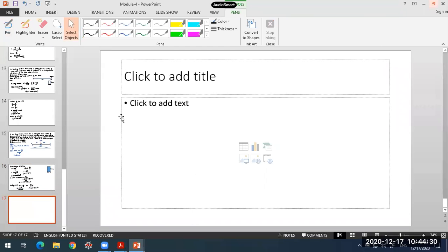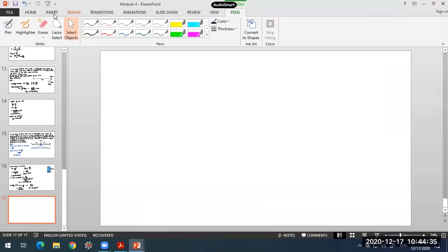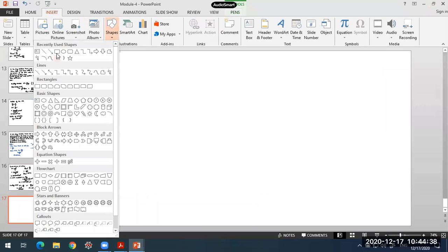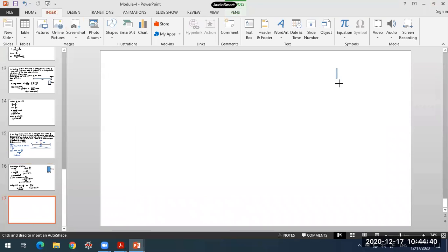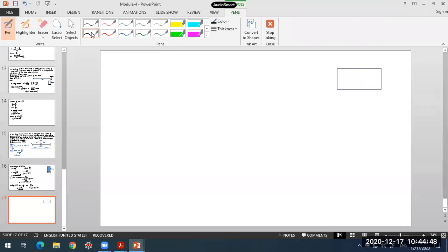When we go to the second case, others, I don't know whether you are calculating or not, it is left to you. In the second case, the cross section is placed in this way. Here the width of the beam will become 200 mm and the depth will become 100 mm. So in the second case, D is equal to 100 mm and B is equal to 200 mm.